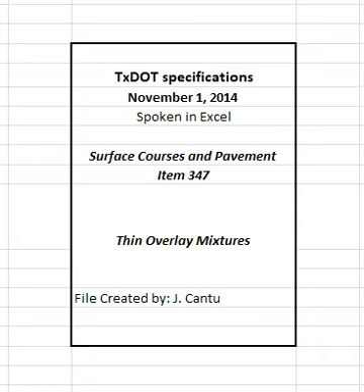4.9.2.4.2 Asphalt binder content. A sublot is defined as out of operational tolerance if either the engineer's or the contractor's test results exceed the values listed in Table 8. Suspend production when 2 or more sublots within a lot are out of operational tolerance or below the minimum asphalt binder content specified in Table 6 unless otherwise directed. Suspend production and shipment of mixture if the engineer's or contractor's asphalt binder content deviates from the current JMF by more than 0.5% for any sublot.